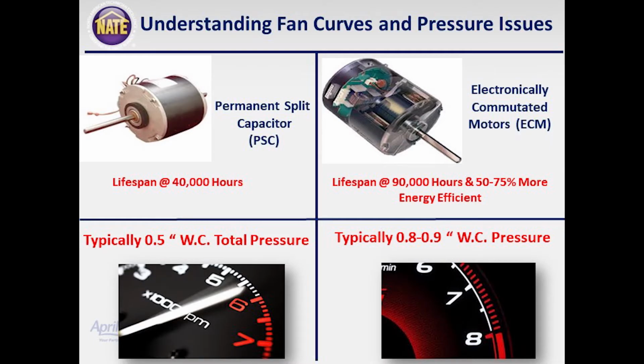This past summer, HVAC manufacturers had to switch from PSC blowers to ECM blowers, constant torque ECM blowers, DC motors. There are lots of energy advantages to this. This makes our case for putting in a high efficiency whole home filter with low static pressure an even more compelling case, because we can see a significant reduction in electrical consumption.